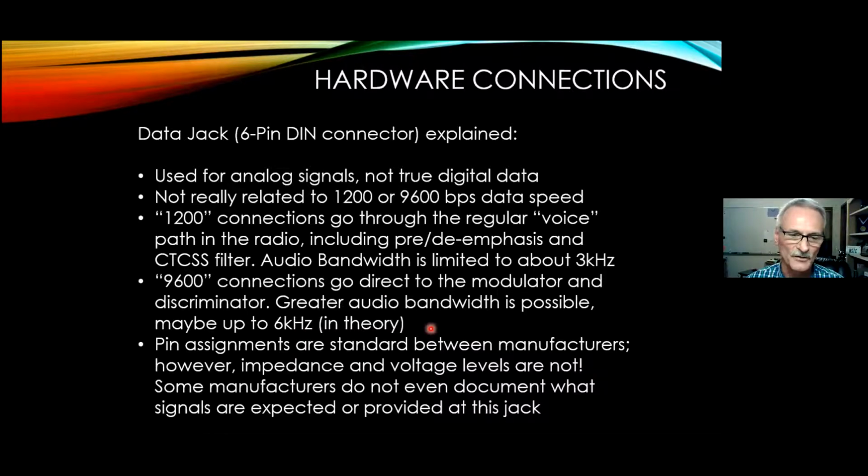on some radios. And so that's where you're going to get the maximum throughput, is if you can utilize the 9600 connections. And I will say, even if you're doing 1200 baud packet, use the 9600 connections. They will work just fine. Again, pin assignments are the same on that 6-pin connector. So, the push to talk lead is always the same pin, but we don't necessarily know what the signal levels need to be.